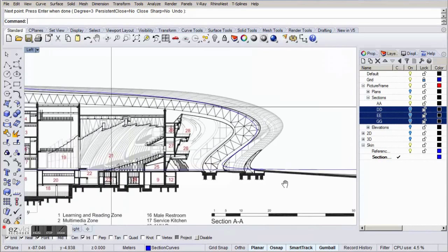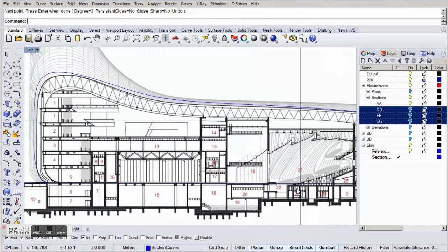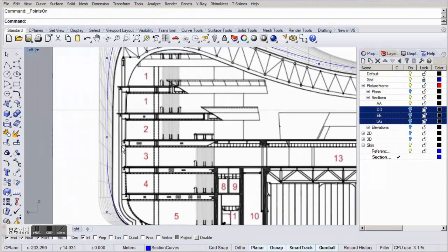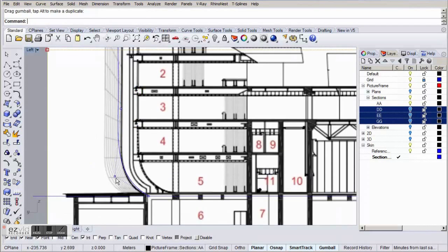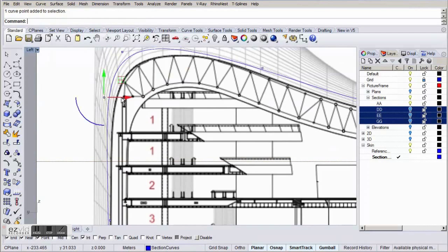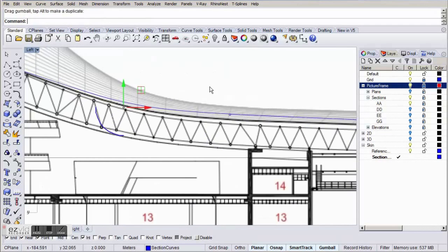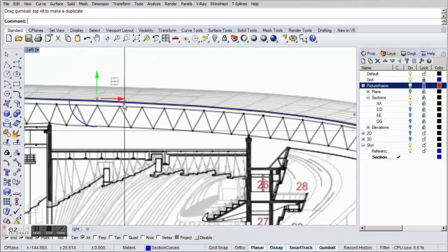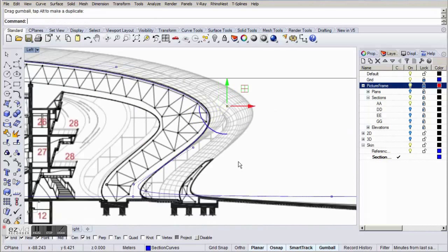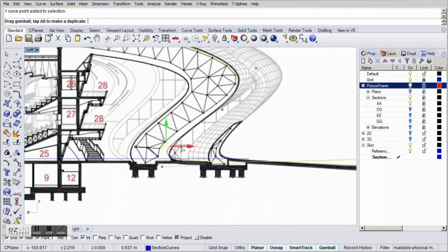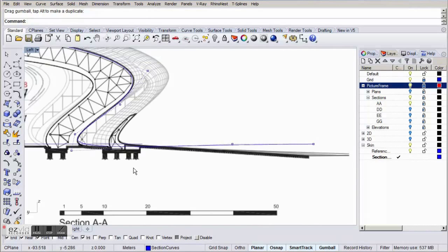Okay, let's select our curve again and let's adjust the control points to get the shape right. Let's select these last 4 control points and make sure they're on the same height using the set point command we used before.